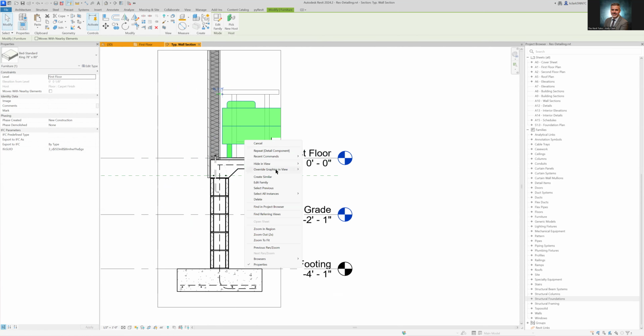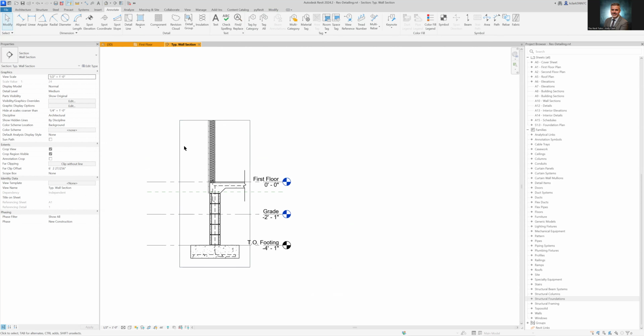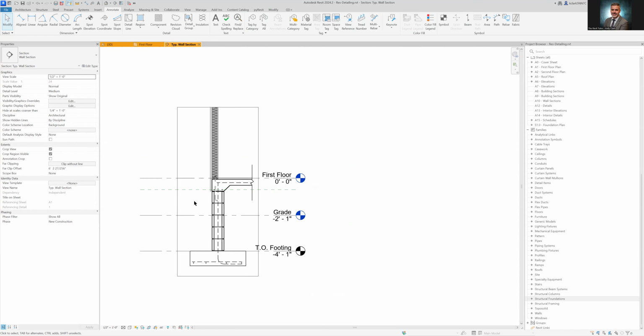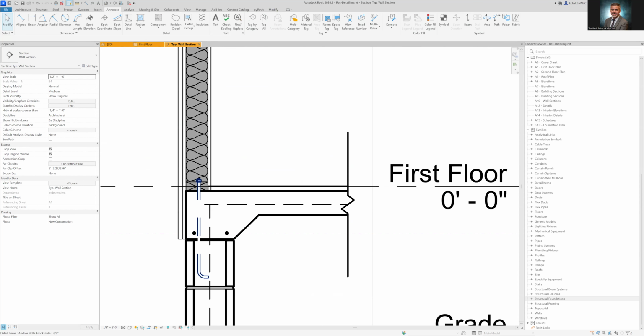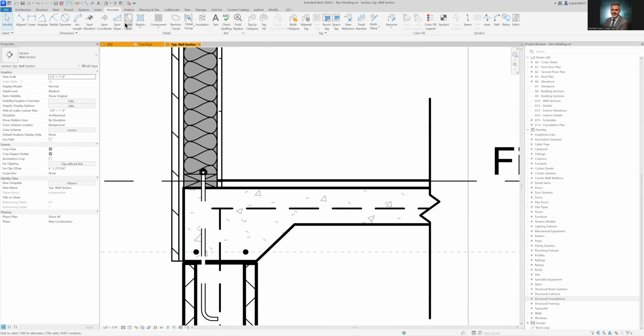And I'm going to turn off that hidden view category of the furniture. It's not relevant for my drafting view here. All right. And then if there were any other lines that I wanted to add in, let's say it should have had a baseboard or something in here that I want to show off, and I didn't want to model it, I can get a detail line or I can get a filled region to show that off.